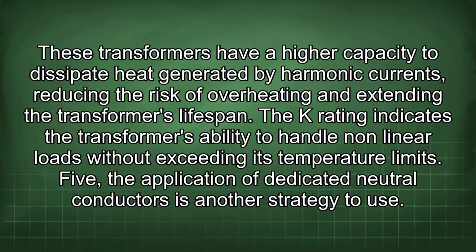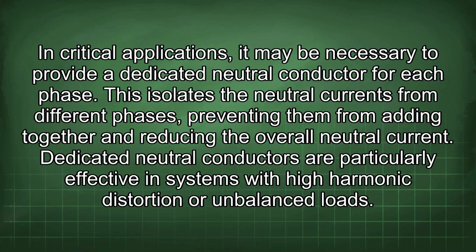5. The application of dedicated neutral conductors is another strategy to use. In critical applications, it may be necessary to provide a dedicated neutral conductor for each phase. This isolates the neutral currents from different phases, preventing them from adding together and reducing the overall neutral current. Dedicated neutral conductors are particularly effective in systems with high harmonic distortion or unbalanced loads.